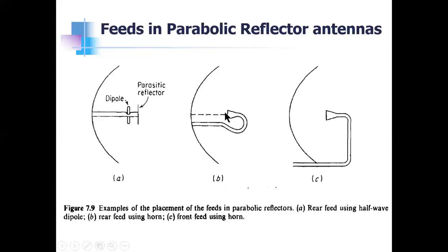Okay, so this aperture illumination at the edges should be 10 dB below the maximum radiation coming out of these parts. It was found that with a primary feed pattern which is 10 dB below towards the edges, the first side lobe in the secondary pattern is in the vicinity of 22 to 25 decibels.